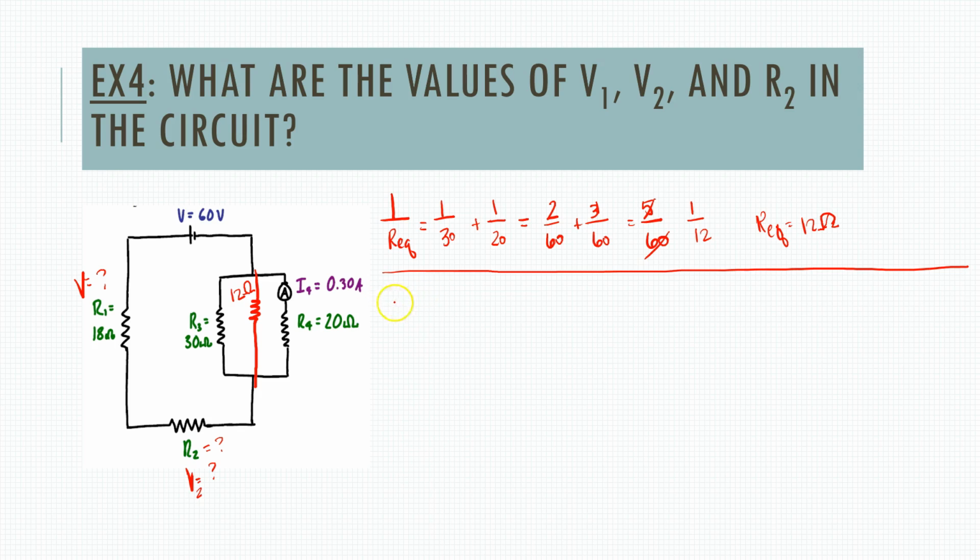So somehow I'm going to have to go about finding the current. If I can find the current in this whole piece, then I know the current at every other point throughout the circuit, because in series, it's all the same. So let's see what I could do here. In parallel, the total current is I1, which, well, let's just do it with these numbers. It'll be I3 right here plus I4. Do I have enough information to do this?